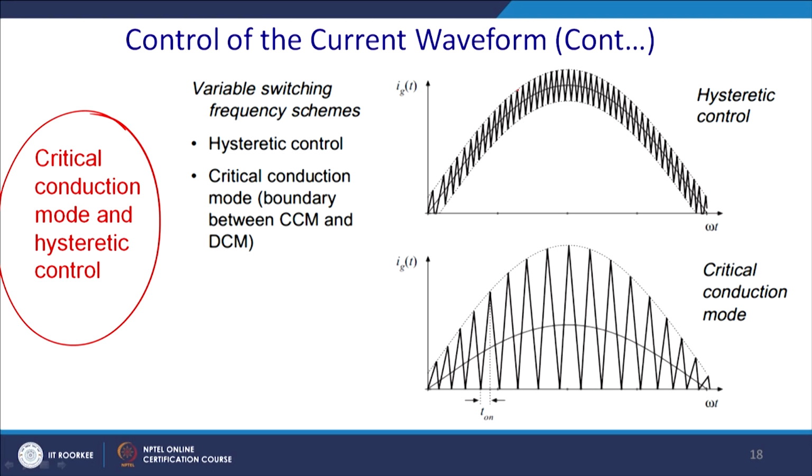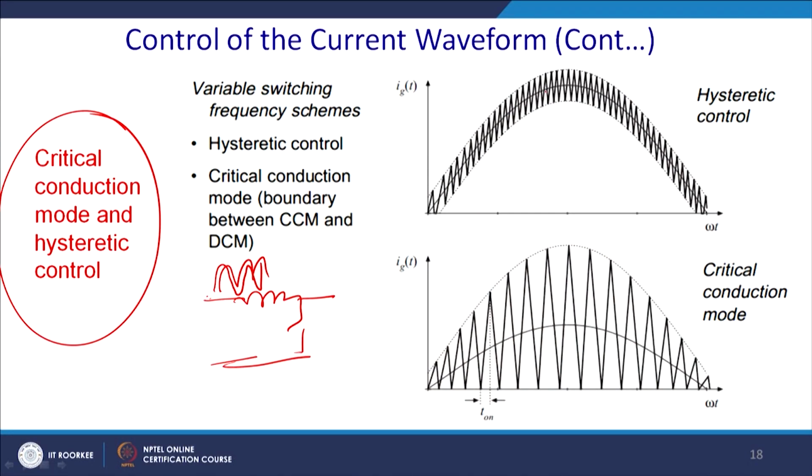What happened, you have this Vg after rectification, you got a ripple kind of voltage, thereafter you have a boost topology. There you generate a hysteresis envelope, which can be generated by a single op amp, a positive or negative band, and you can keep the current within the positive and negative band. So, you can have different kinds of band. This is called actually constant band.